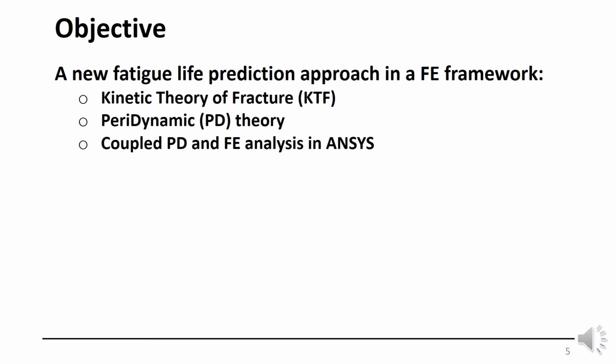So our objective in this study is to come up with a new fatigue life prediction approach in a finite element framework. So we will use kinetic theory of fracture, we'll use peridynamic theory, and we're going to couple peridynamics and finite element analysis in ANSYS.